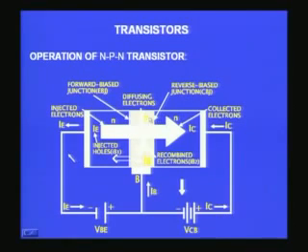But you can also have another condition. The electrons in the base region, as you all know, are minority carriers, because the base in this case is a P type semiconductor. The electrons are pushed from the emitter, and these electrons are minority carriers in the P region or the base region, and therefore they will find it very easy to cross over to the collector region, because for them there is no potential barrier between the collector base junction.